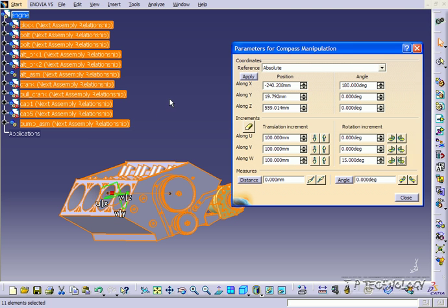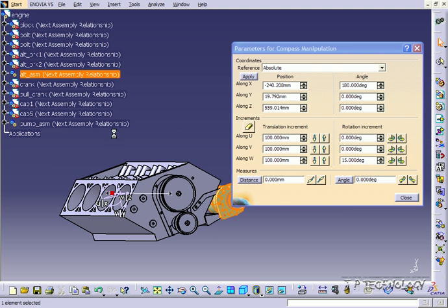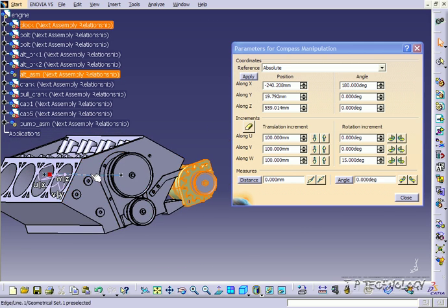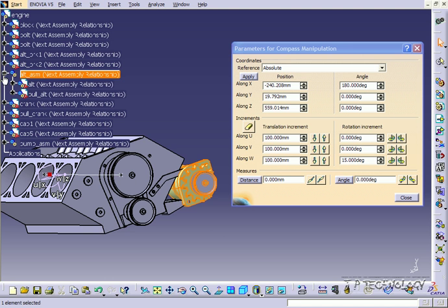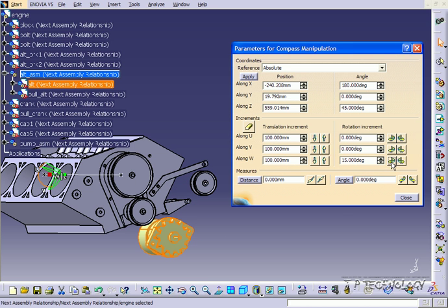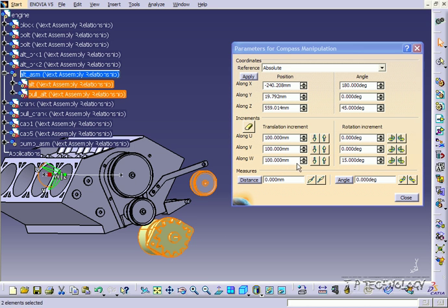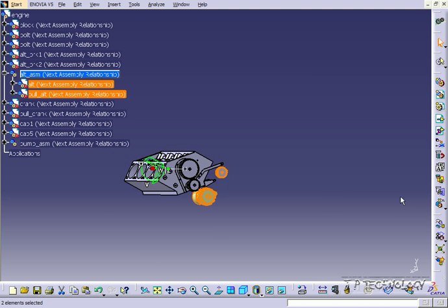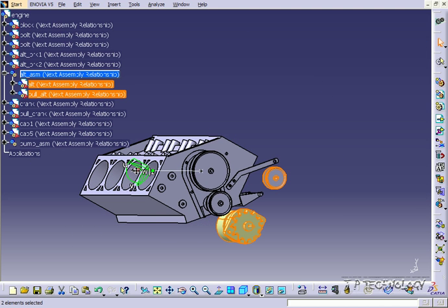And again, we can do this to a smaller assembly. So double click the alternator here. And we're still going to use this as our axis point. Open it up and let's just rotate this one guy. And you can see that only he is rotating. And as we select both, we're able to rotate both at the same time. So again, this works by using this axis that we've created. And this is going to create a consistent axis, so every time we go to rotate, it's always going to be the same result and the same rotation that you get.